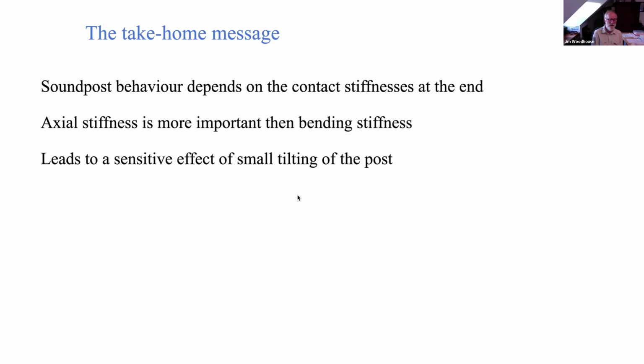Making a small shift to one end of the post may make a surprisingly large effect, may have the effect of a much bigger shift in the post because of this effect of the contact stiffness being bigger on one side or the other in a way that you can't guess and you can't see by looking at it. The tighter the post, the bigger those contact stiffnesses are, and potentially the more sensitive it might be to this kind of thing.